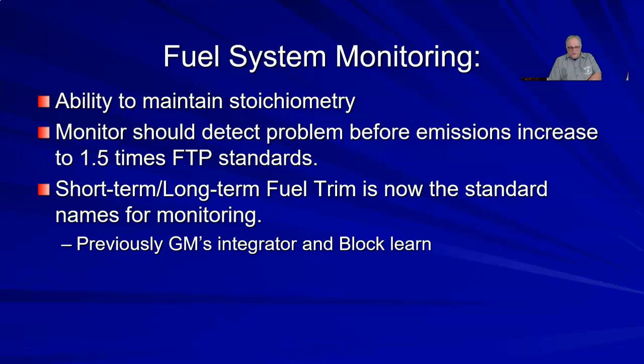If oxygen sensor voltage goes low, short-term fuel trim percentages start to rise. If O2 sensor voltage goes high, above 450 millivolts, short-term fuel trim numbers or percentages go low. Literally what it's doing is increasing and decreasing the injector pulse width to add or decrease fuel to compensate for the rich or lean condition.